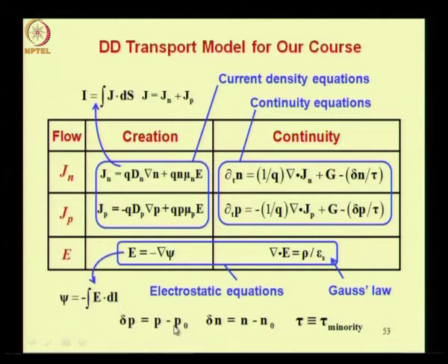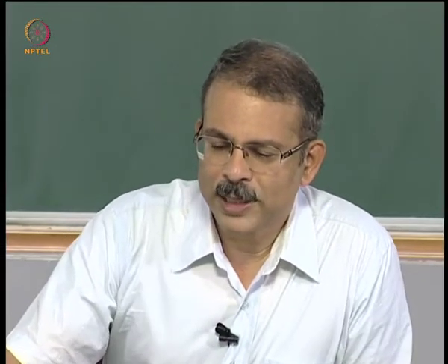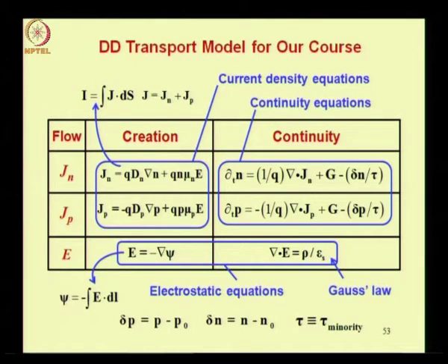We have explained that in most cases the excess carrier concentration of electrons and holes would be approximately equal, because in the semiconductor regions which are neutral or quasi neutral, the excess holes and electrons are generated in pairs. However, to take care of isolated instances where the space charge neutrality condition may be violated, we have retained delta n and delta p as separate symbols rather than using the same delta in both equations.